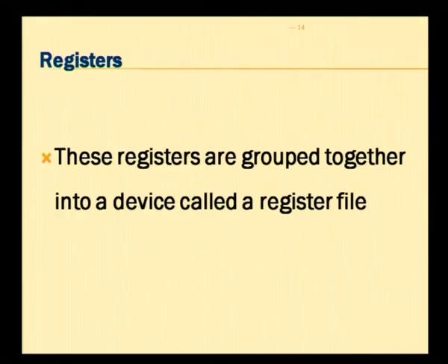And normally, these registers are grouped together into a device called a register file. So, we normally do not talk about just registers, but we talk about a register file. What we mean by a register file is that it has a set of registers in it, and each register in this register file will be individually addressed, which means I can specify which register I want to store into or read from. You will normally have a facility to do that. Now, coming to instructions.